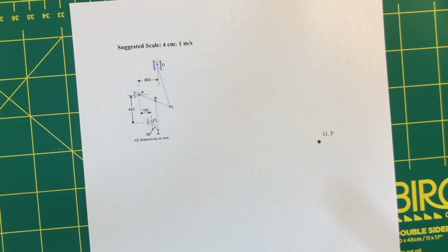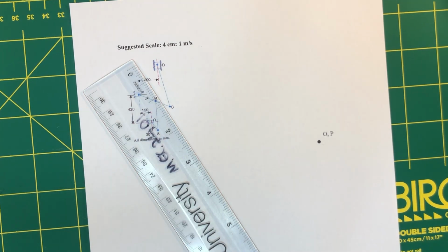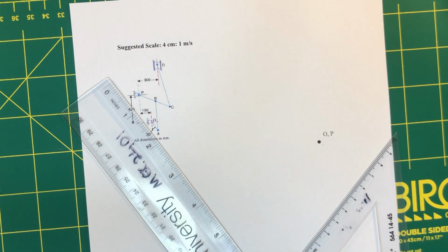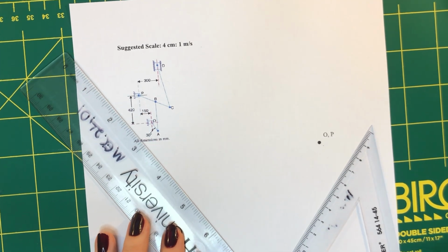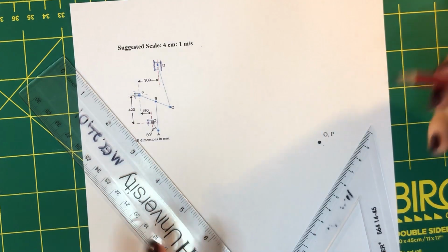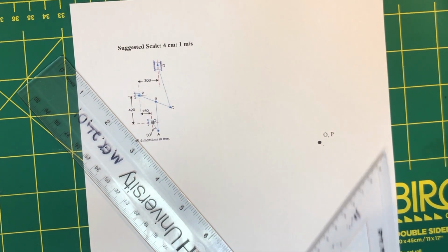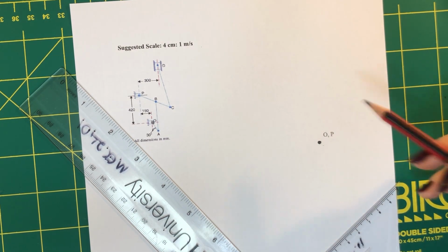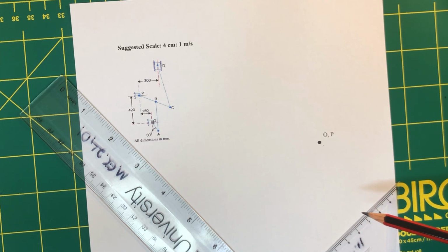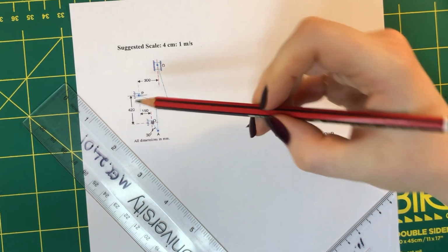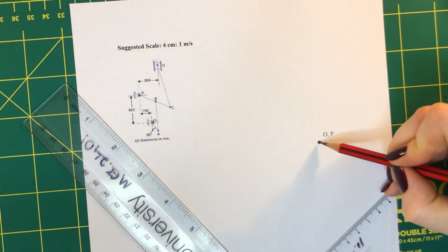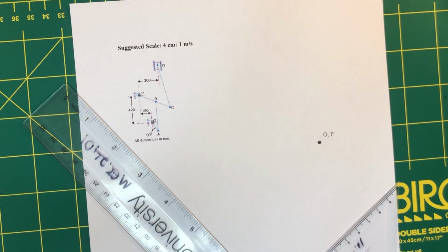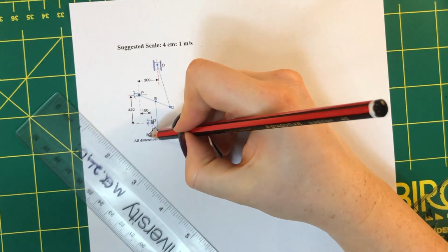Velocity is perpendicular to the link because that's causing its movement. So our lines in this diagram are all going to be perpendicular to the links. For OA, we have fixed point O. This technique is used universally, where you combine all your fixed points into your starting point. There are 2 fixed points in the diagram, point O and point P, and they've been combined into this starting point. We have the link OA.